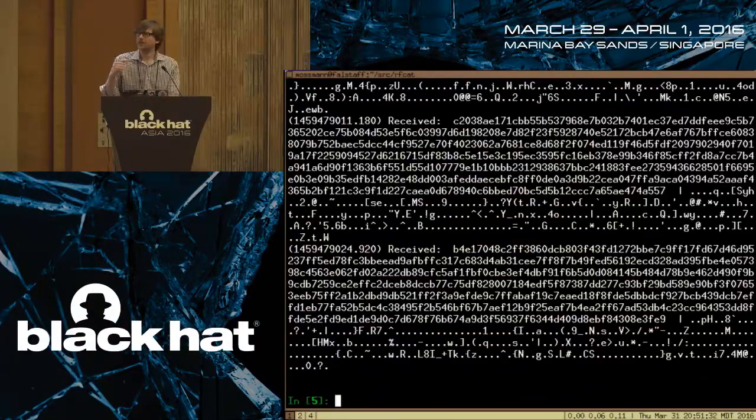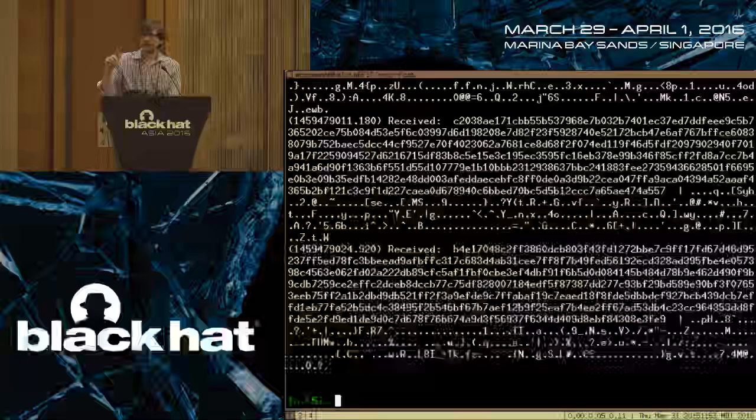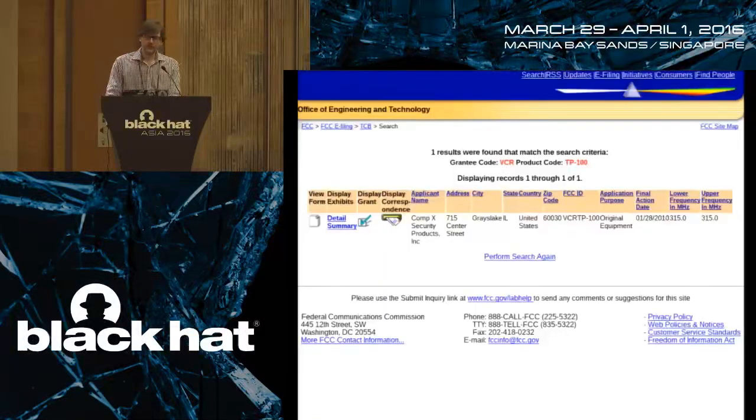The reason it's not doing anything, probably the main reason, is that there are two reasons. One is that it's expecting that a packet starts with a preamble. By default, the wireless transceiver chip that's on the Yardstick 1 expects to see a preamble of alternating symbols at the beginning of the packet. So it's expecting to see on, off, on, off, on, off, on, off, or 1, 0, 1, 0, 1, 0, 1, 0. And we don't actually have that.